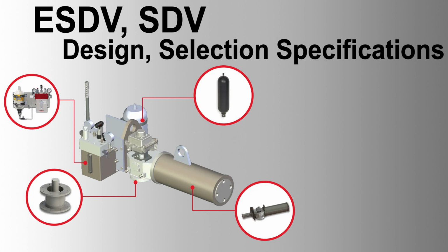Calculation data, required data: suppliers must provide detailed calculation data including valve breakout torque, running torque, reseat torque, stem maximum allowable torque, actuator sizing, fatigue life, and MTBF, mean time between failure. Actuator mechanical design, orientation and position: operation should not be affected by actuator orientation. Component strength must withstand maximum operational loads. Compatibility: ensure mechanical compatibility and suitable coupling support brackets.